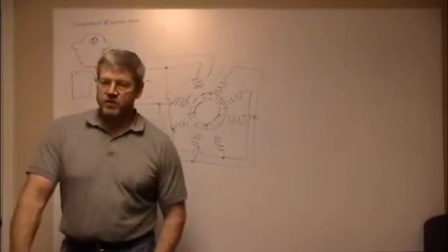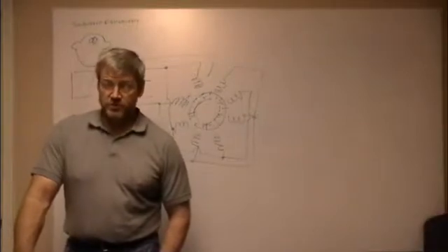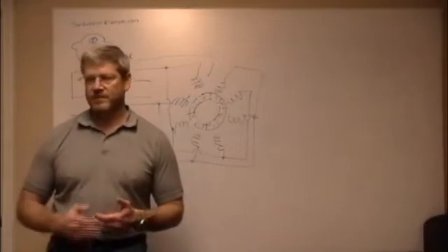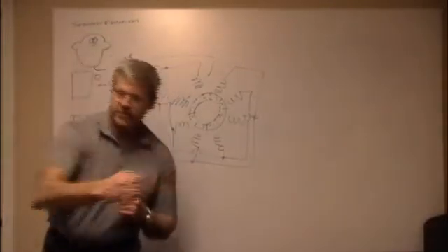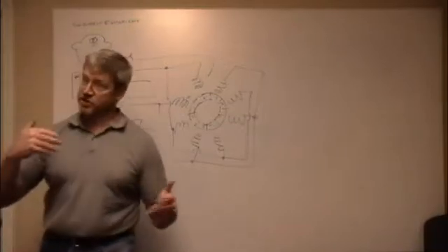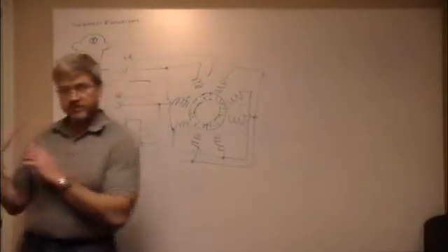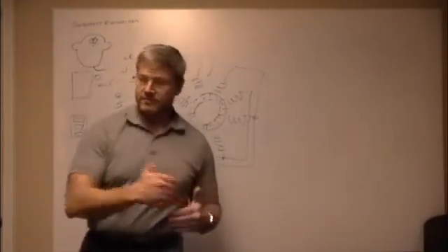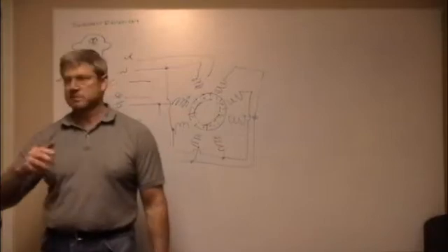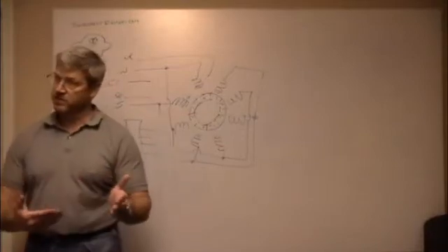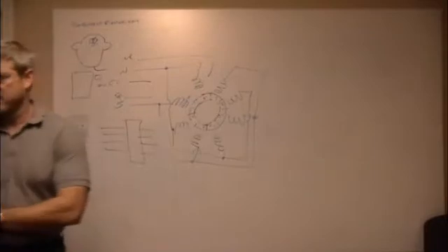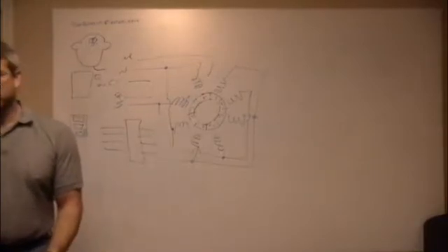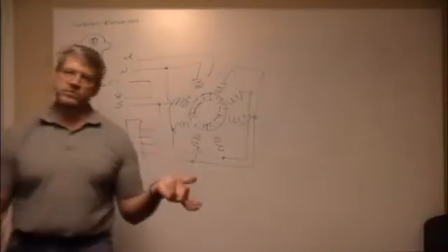The deal with a servo is, to get a good servo loop for real control, like you'd want on a CNC mill, there's a lot of software with that, because you can't just go and stop. You've got to do a trapezoid: speed up, get things up to speed, get to that point, and then slow down before you get there. And with a stepper, you just go tick tick tick tick, and eventually you get there, but it gets there slower. But you don't have to change speeds, and some steppers can move really quick. So you start getting into price points. Do I want to do it this way, or do I want to do it that way?